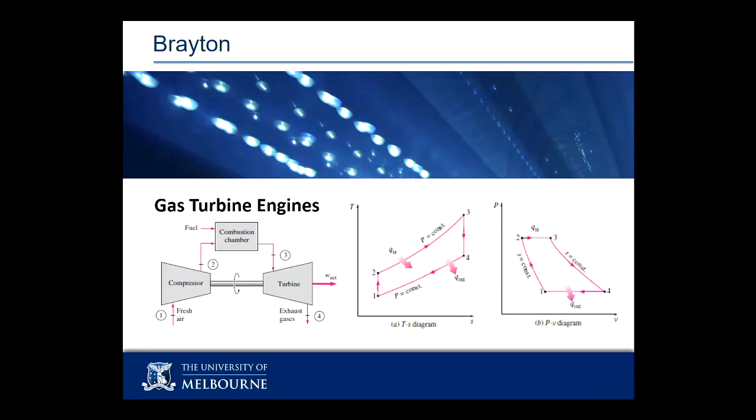So the gas turbine cycle, before I get to the Otto cycle, it's one of those Friday days. The gas turbine cycle does what almost all heat engines do. It takes some air, squeezes it, heats it up, gets some power out of it, and lets it go again. The old sentence that used to get added to this is suck, squeeze, bang, blow, which is to say, coming in the front comes the air, compress it down, squeeze, bang, set fire to something, add heaps of energy, and out the end, blow.